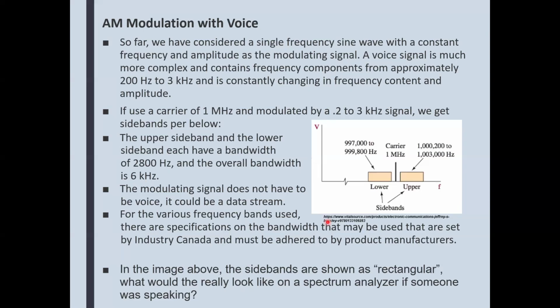And it's interesting because if somebody is transmitting on the upper side and you have your tuner set to lower side, you will hear just a little bit, but it's almost distorted. It's almost not there. So okay, I wonder if he's transmitting on the upper sideband. Switch it, and boom, the whole thing becomes alive.